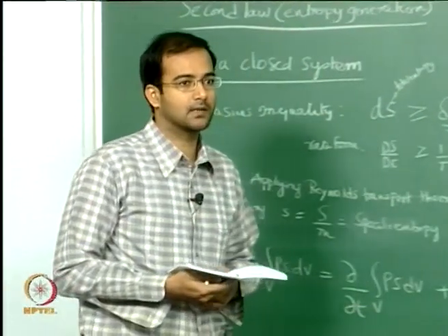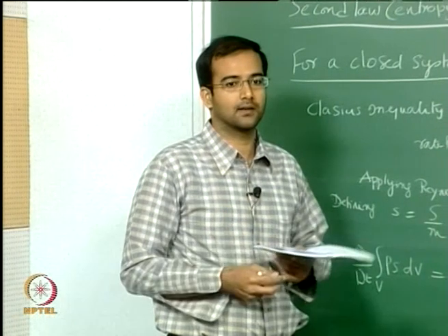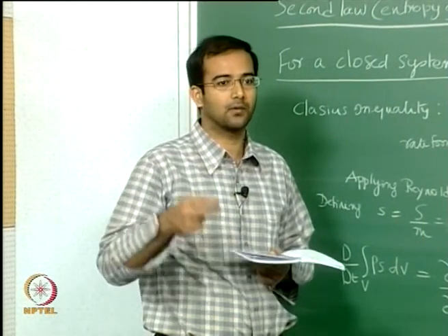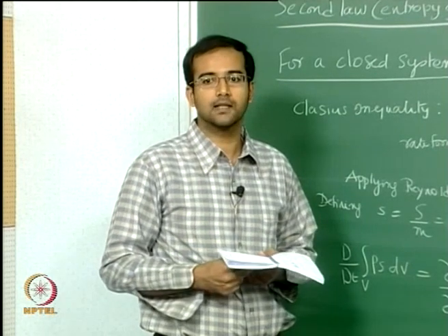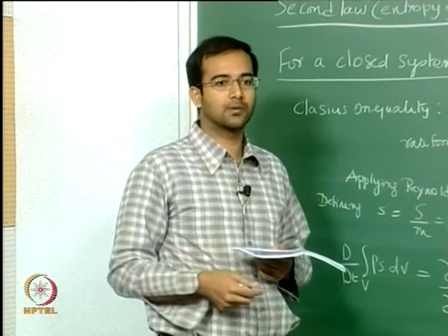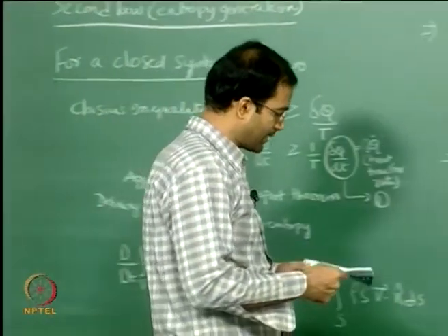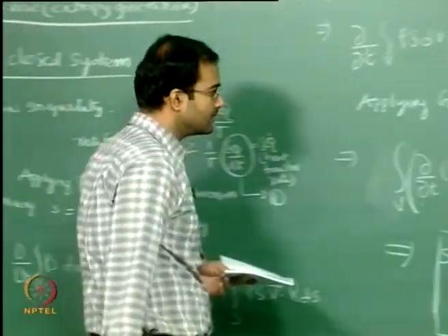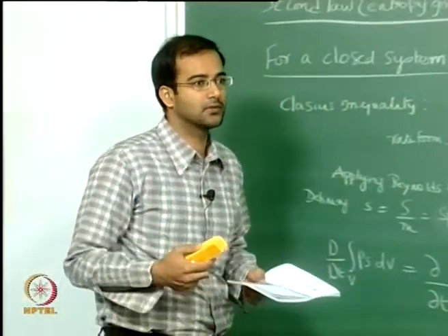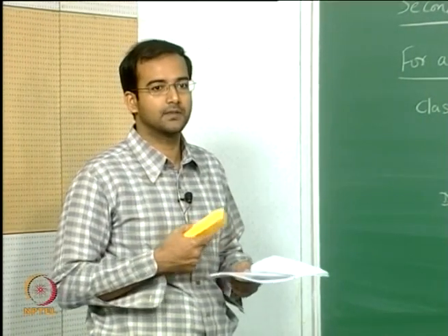If you want to overcome that, we can rewrite the Navier-Stokes equation into what is called a stream function vorticity formulation, and that is very useful when you are looking at 2D incompressible flows. There you have only 2 variables, 2 equations, you can solve that straight away, and the solution is also slightly simpler than solving the Navier-Stokes. So we will quickly derive that formulation today, and in fact in the project that you are supposed to do, you will be using those 2D stream function vorticity equations with the energy.